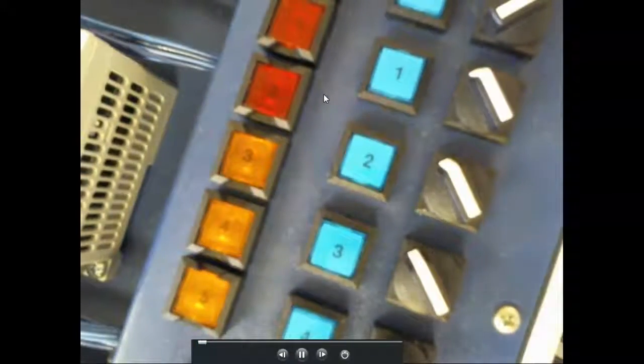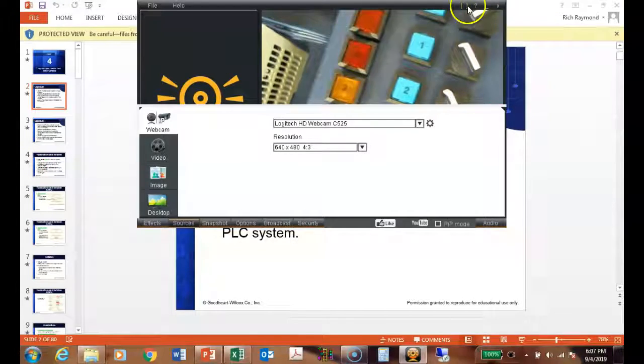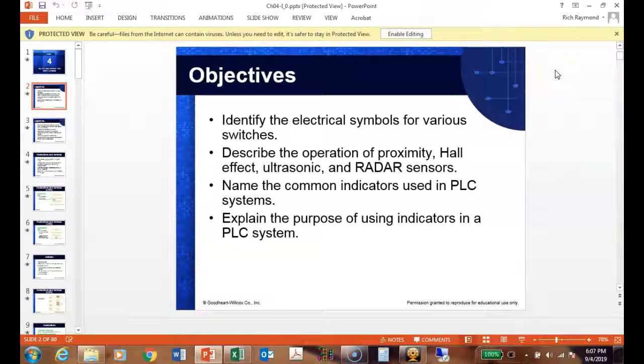Now what advantage is there to a fixed PLC? Everything's built right there. Well, they're all set up basically the same. We'll look at that. Fixed PLCs are the cheapest. They are not expandable. You get what you pay for, period. I cannot add inputs. If I need more inputs, I cannot add more inputs. I cannot add more outputs. I cannot add analog to this. I can't add anything. I get what I pay for.